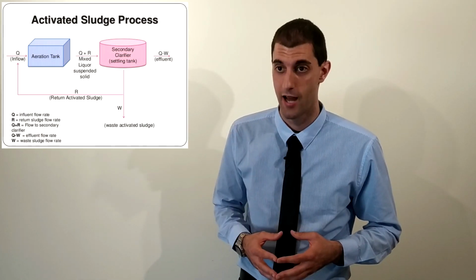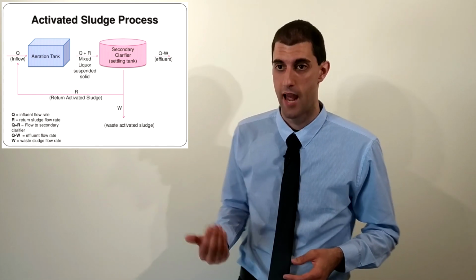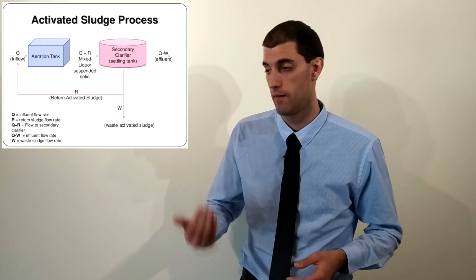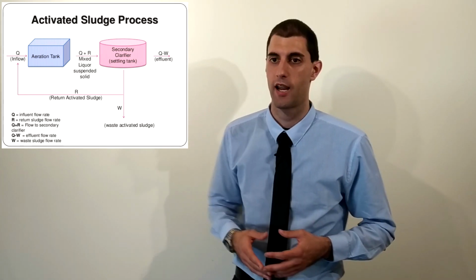After the bioreactors, wastewater continues to flow to the secondary clarifier, which operates in the same manner as the primary clarifier. Some of the solids collected in the secondary clarifier, known as return-activated sludge, are sent back to the aeration tank to treat more wastewater, and the excess waste-activated sludge is pumped to another location in the plant for further treatment.